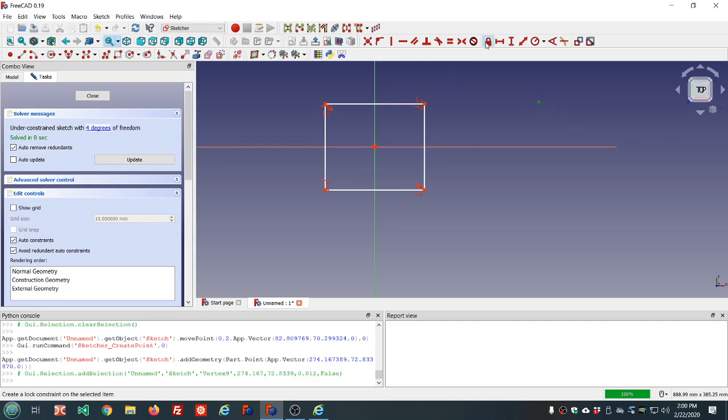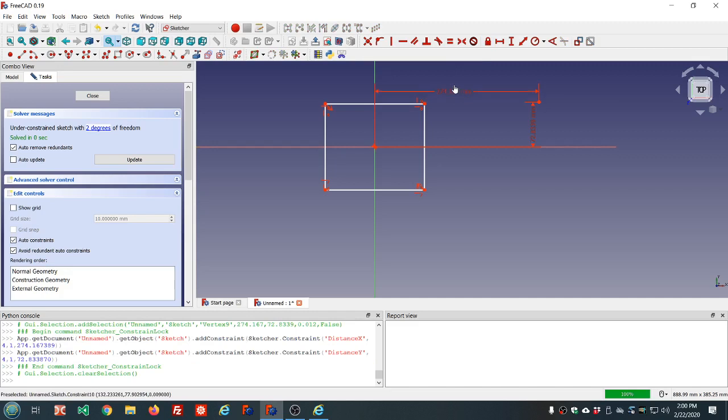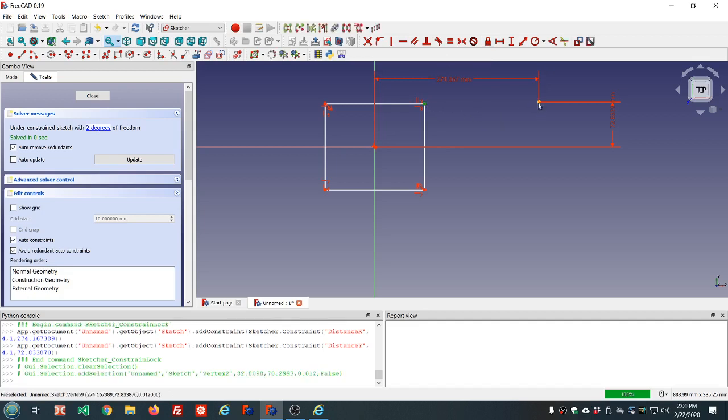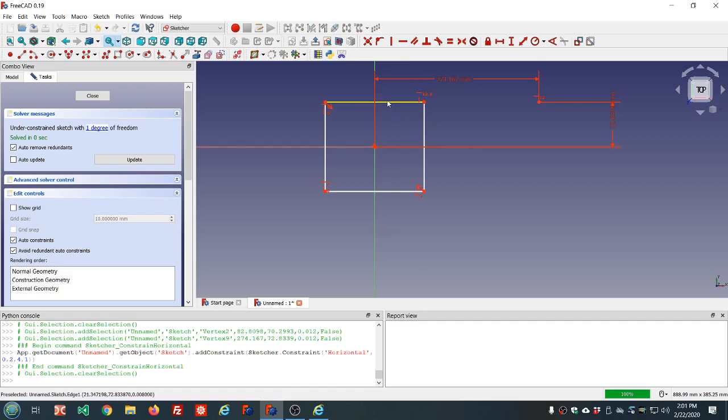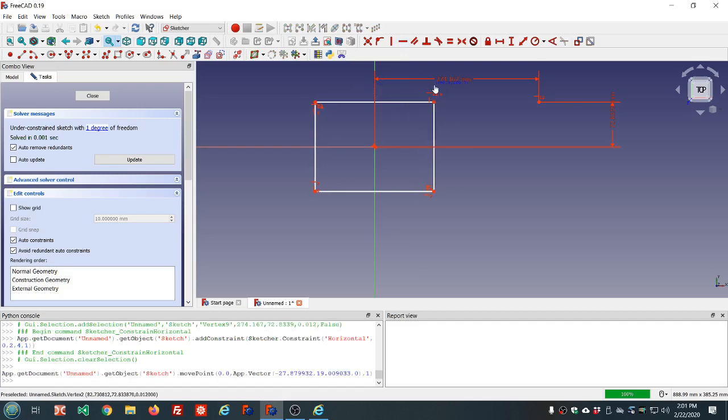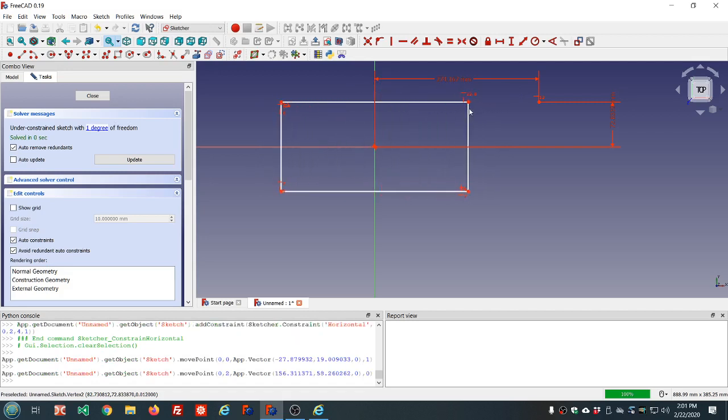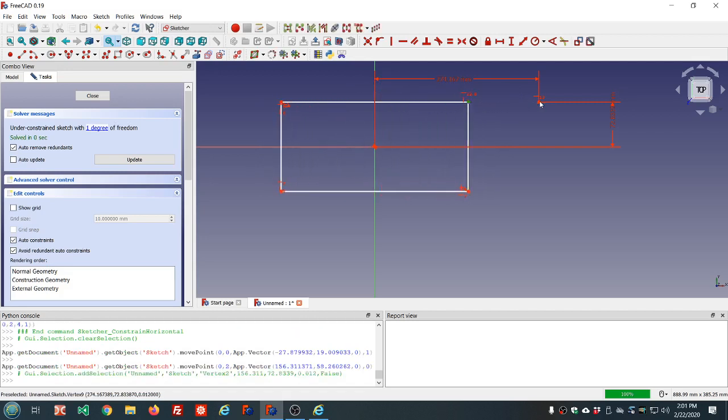And we can lock this one in using our lock constraint, which just all it does, creates 2 of these with the origin. It's just a convenience, so we can create them both at once. Lock it into place, and now we could create a horizontal constraint to both of those points. And now we're constrained so that this point is horizontal with this point.